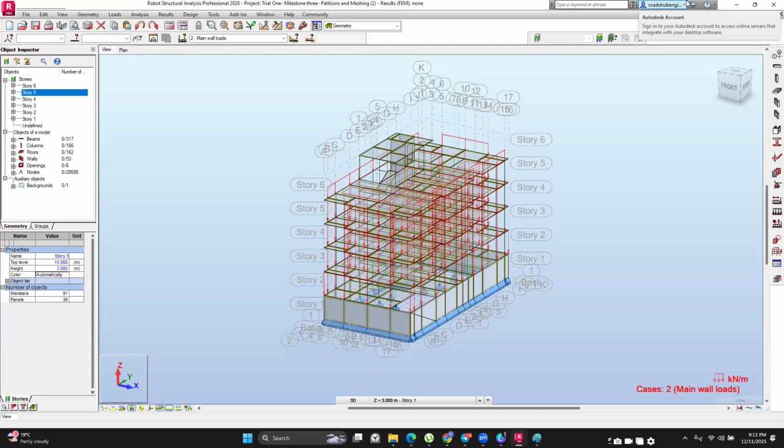These 98 kilonewtons are not going to be acting on one part of the slab. It is going to be acting as an area load. So how do we get the area load? We are going to assume our tank has a diameter of 2.1 meters. So you just divide this 98.1 by the diameter of the tank. The standard diameters for a 10,000 liter tank may differ from manufacturer to manufacturer, but I think 1.9 to 2.1 will suffice. So I'll go with 2.1.